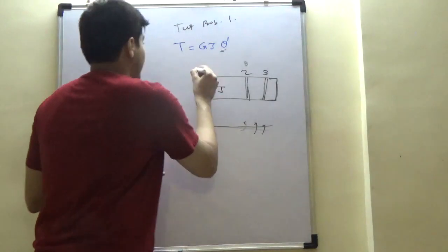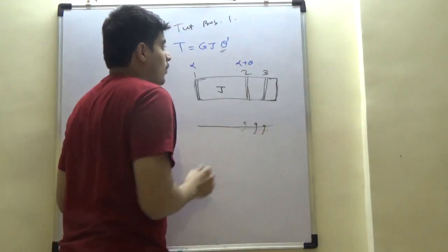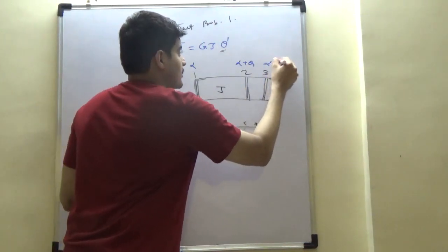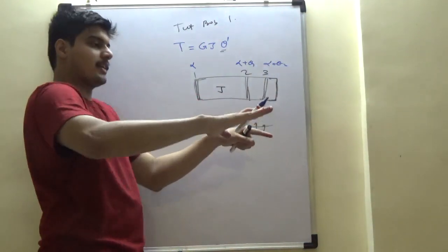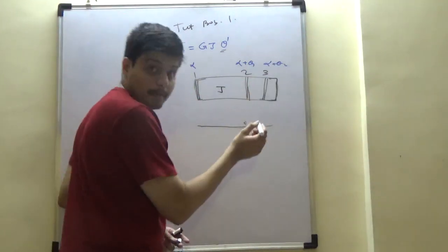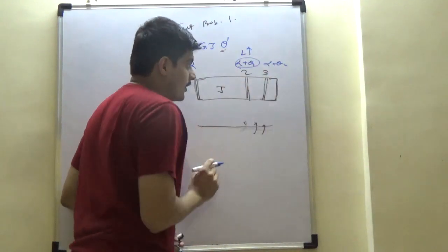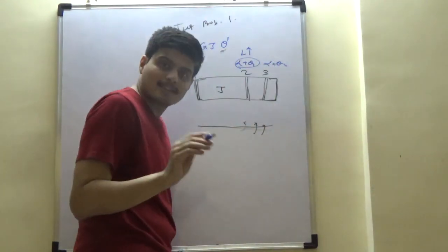So at section 1, the angle of attack is alpha. Then here it is alpha plus theta 1. Here it is alpha plus theta 2. So as the wing is getting twisted, it is actually seeing more angle of attack. That may be good or bad. If this increases, lift goes up. Right? Imagine these are small enough so that it is still not stalled.